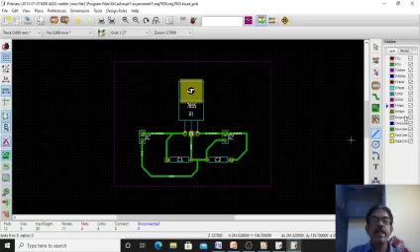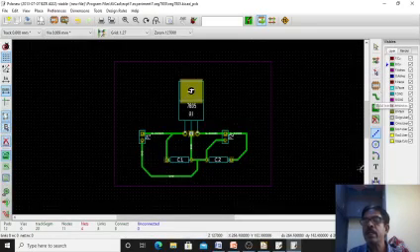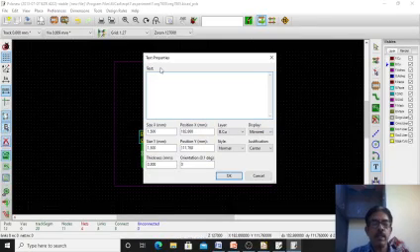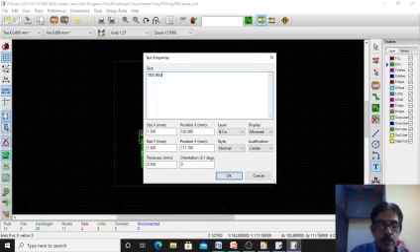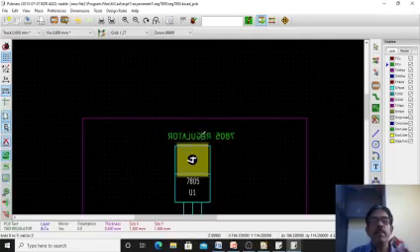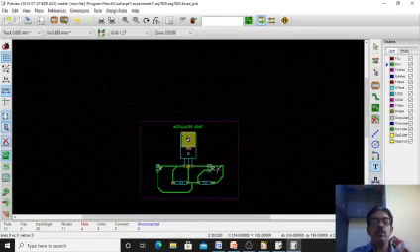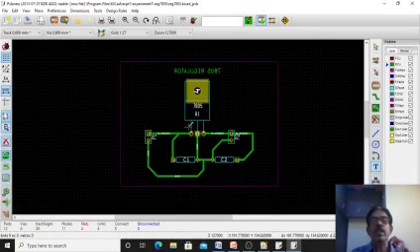Okay, then name this circuit as 7805. Again go to back side copper. Earlier I went to front mask, now you go again to back side copper, and then T. Okay, add text on this and type the name, that is 7805 regulator. I have typed it. Okay, then say OK. Then it will be coming as a mirror image. Okay, place by zooming it, you place anywhere you want. Okay, for example I have placed here. So this is the diagram. PCB layout is now ready.